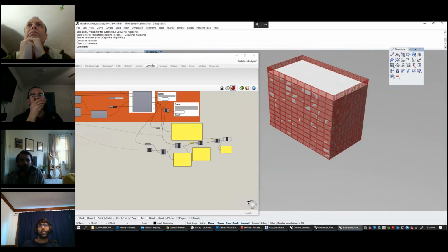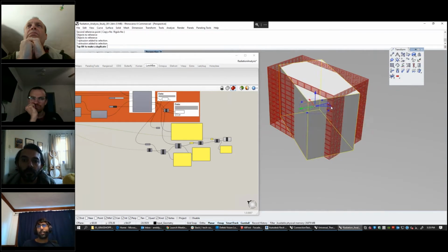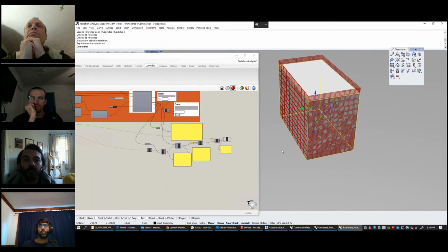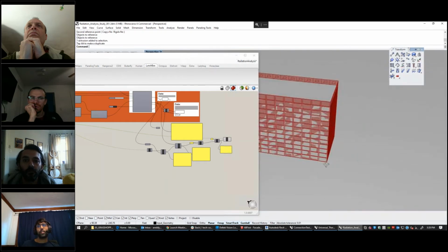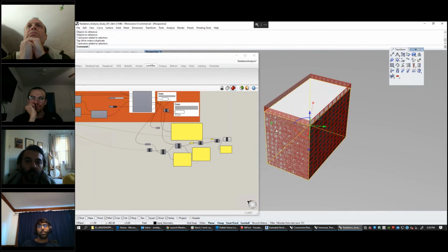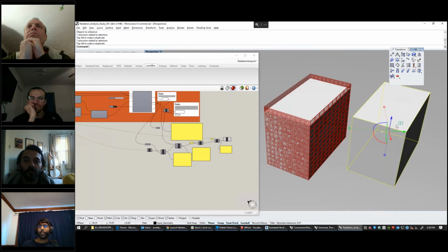So where on the north face you're basically not getting that much sun, you can actually start to have big windows. And now we can actually manipulate our model depending on the sun orientation, and it'll actually start giving us some different results, right? So you can start to see how things would change. But when you're doing just a flat face, obviously each elevation for the most part is going to be changed, especially when you don't have any context. I don't have context plugged into this model. I can actually plug them in. Let's plug some in and really see what that does.